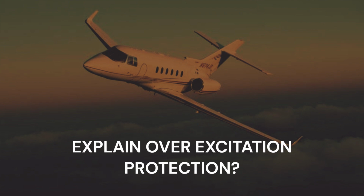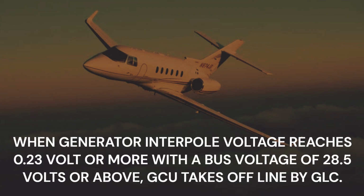Explain overexcitation protection. When generator interpole voltage reaches 0.23 volt or more with a bus voltage of 28.5 volts or above, the GCU takes the generator offline by the GLC.